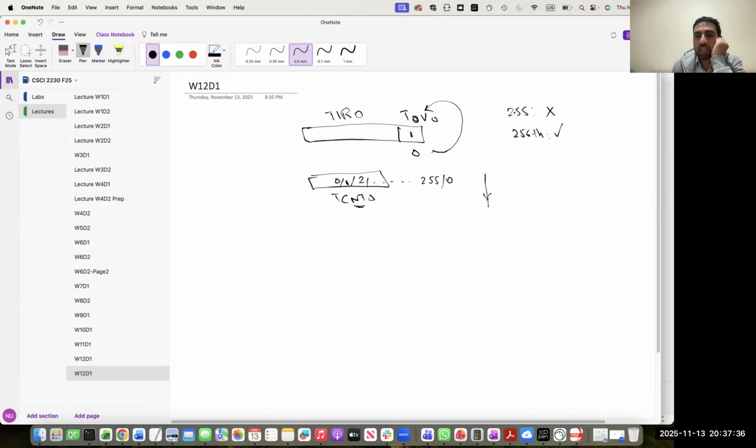But what is the important observation here is that the microcontroller is tied up for 255 cycles and can't do anything else, because it is continuously checking, or polling, the overflow flag, right? So yes, we are able to detect if an event has happened, for example, the flag is set, but this polling approach is not good in terms of using the resources.